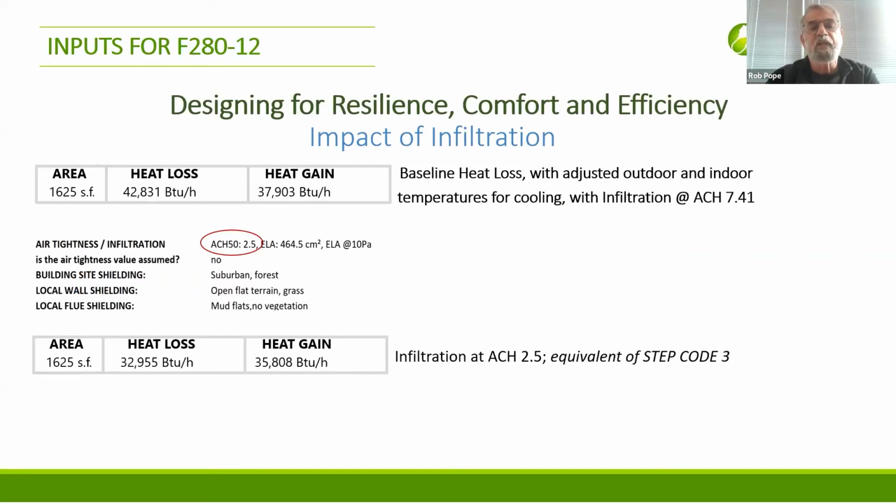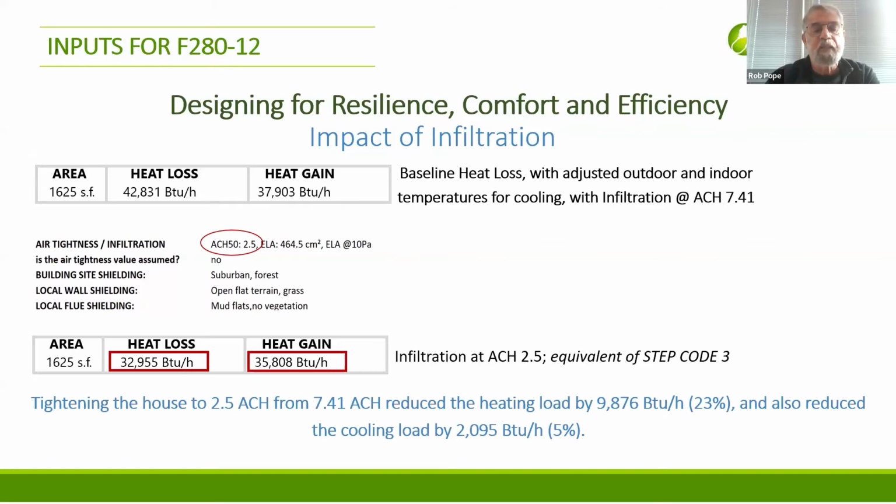Designing for resilience, comfort, and efficiency. Infiltration is huge. We went from 7.41 to 2.5, which is your typical step 4 house, right? Or step 3 house. And look at the difference it makes.